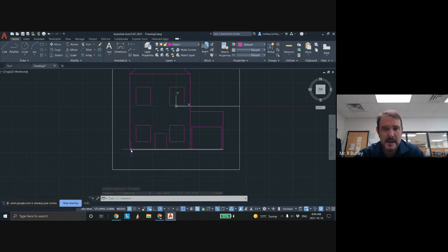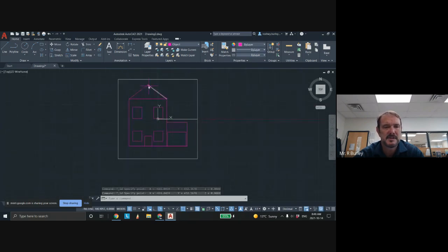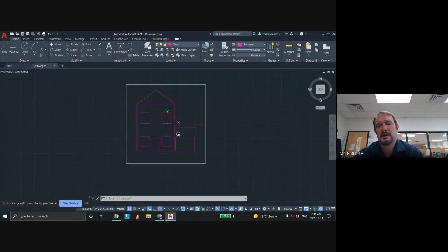Then you would drop your pen down. Then you'd send your robot up to this position. So you come up here and go ID point, and you'd send your robot to that position. Then you'd send your robot wherever you like, that position, then this position, then back to this position. Then you lift your pen up and you drive the robot way down over here. You could drive down the same line, or it's faster to go on a 45-degree angle to here, and so on. So that's how we program the robot the simple way using AutoCAD.